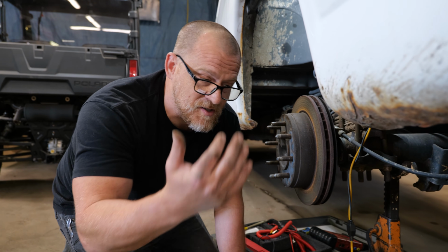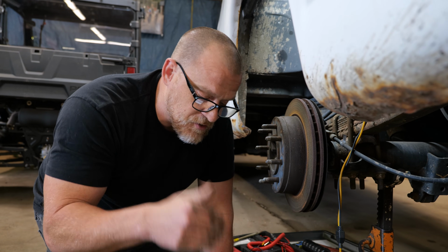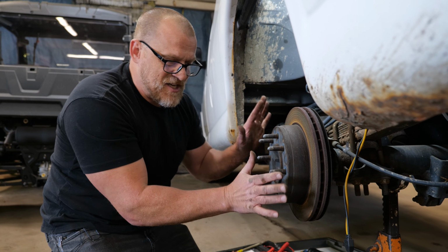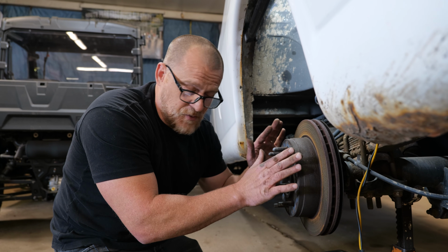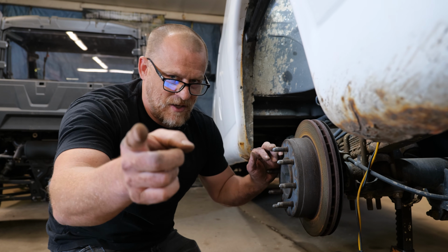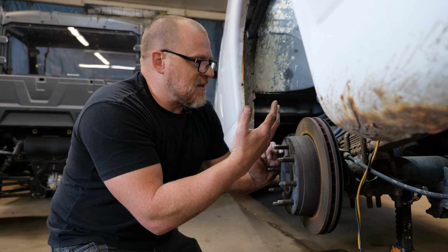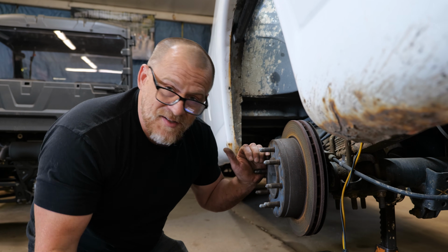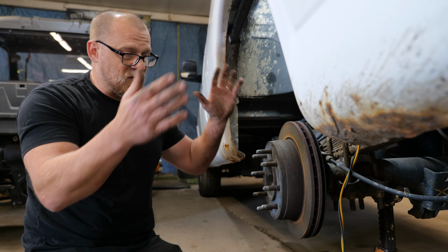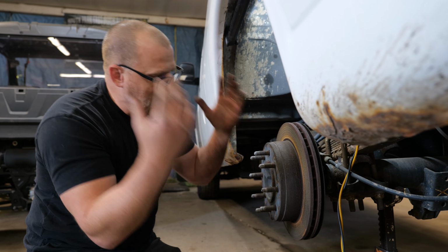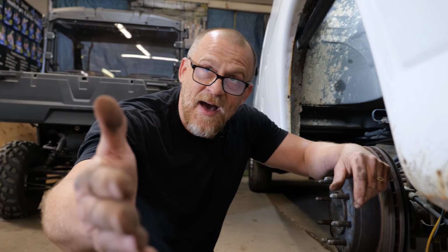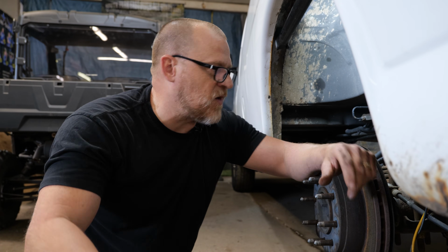The problem was that voltage level, computers using that bias line to determine opens and shorts. There's not even a signal here going on. This makes its own voltage on a VRS type sensor. Chapter 21. And the computer doesn't need the wheels to turn to recognize a fault. It recognizes the fault without the wheels even turning on a sensor that makes its own voltage. How is it doing that? Bias voltage is how.